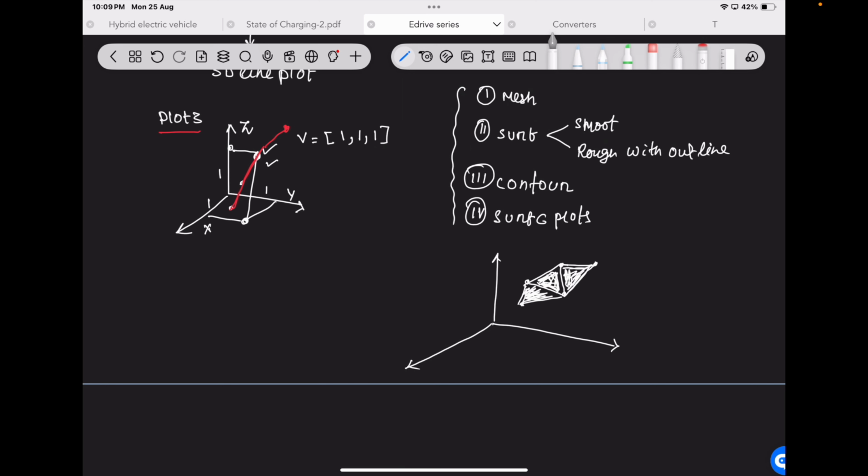So basically when you jump into a surface plot, it is an actual surface that is visible from all the viewing angles, and you can feel it in the MATLAB environment. But for this, you need to create a meshgrid surface. So meshgrid is like, suppose you have 0 to 5 over here, the values for the x-axis, and the same 0 to 5 here for the y-axis.